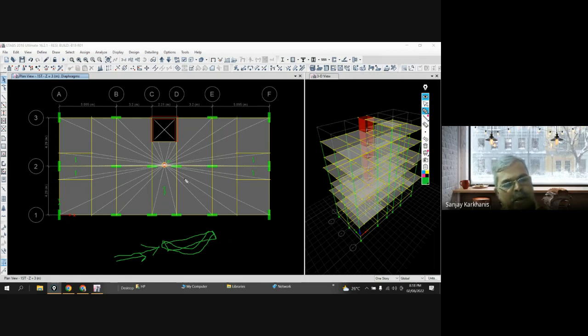It can happen after applying, right? Yes, sir. It can be like this, right? You don't want this movement. You want this to move in one line, this or this or this. And that's why you are saying that this is rigid. This is rigid, and that rigidity is understood by this software by applying the diaphragm rigid constraint. Clear?